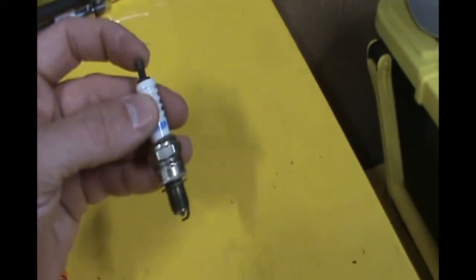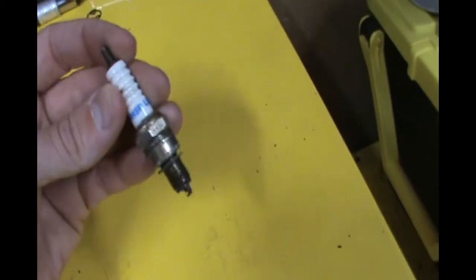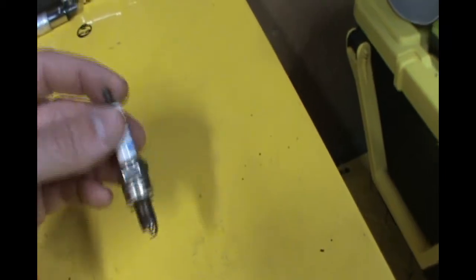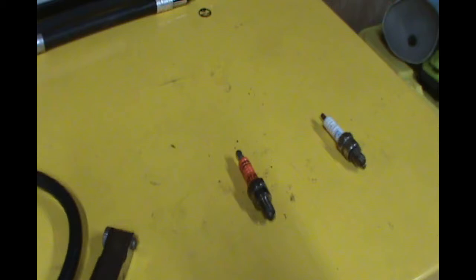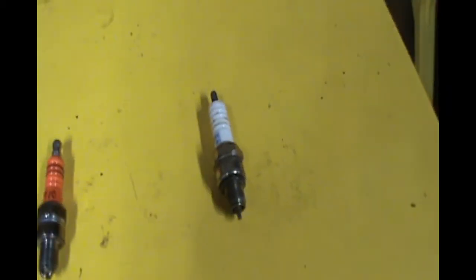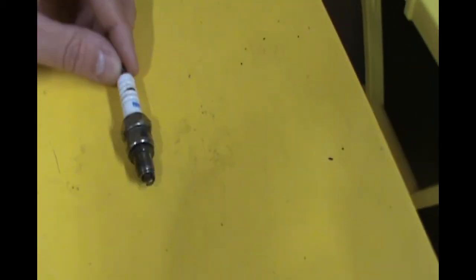We have a thing called a coil. Most vehicles now are what we call coil on plug, which is very, very similar to what we're running on the dune buggies these days. And a coil on plug is really, really simple. Battery power gets sent to a coil, the coil amplifies that battery power, and then it receives a signal on when to discharge that power, and it sends a shock, a high energy shock, through this spark plug.